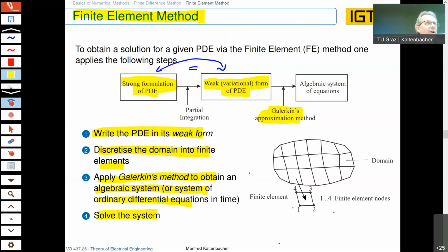We just get it at the nodes of the finite element, the same as we had at the nodes when we did the finite difference approximation. It's not the Shannon theorem, but it's also very similar to an analog-digital conversion, where we also don't actually know what our measurement signal is between two digital values after the time discretization, after the conversion from the analog signal to the digital.